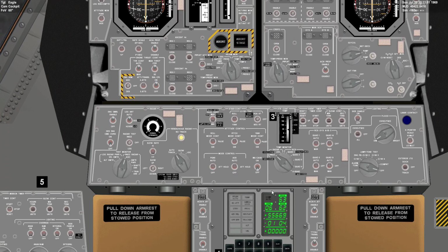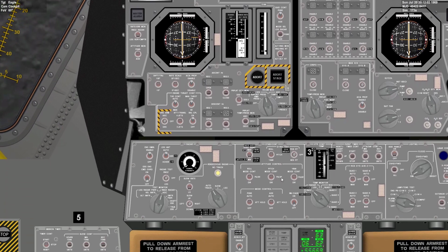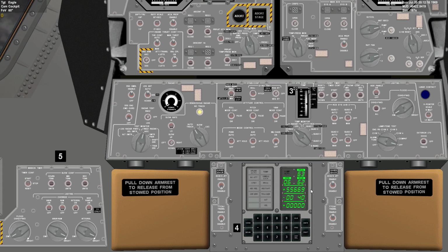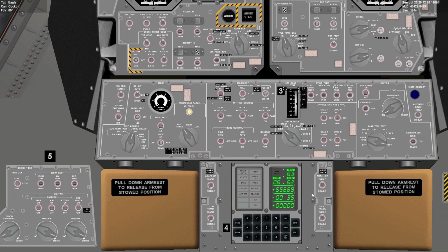It also shows up in channel 31, if the hand controller is sufficiently deflected. And those bits in channel 31, if any of them become set, if the AGC has requested it, they can trigger an interrupt, hand direct. And so I had to get all of that working for the hand controller to properly work.